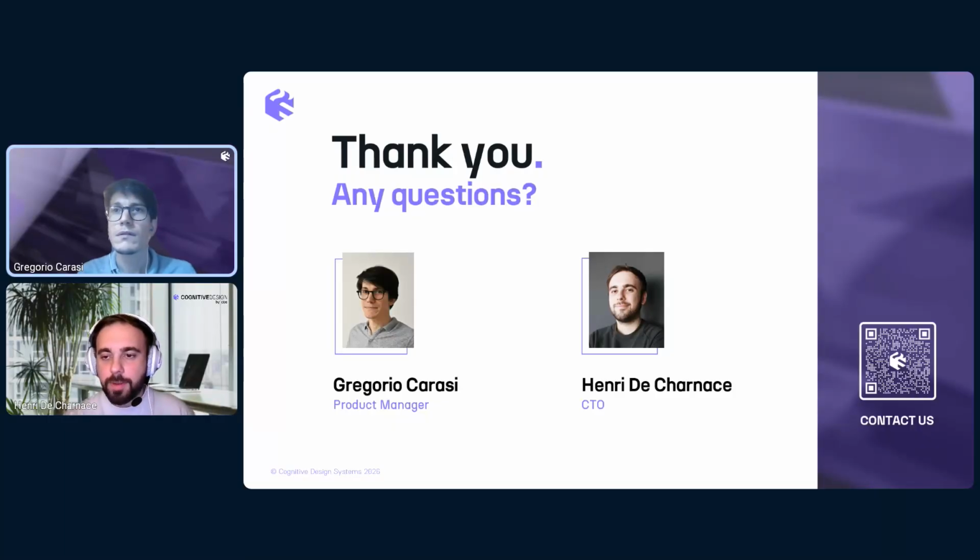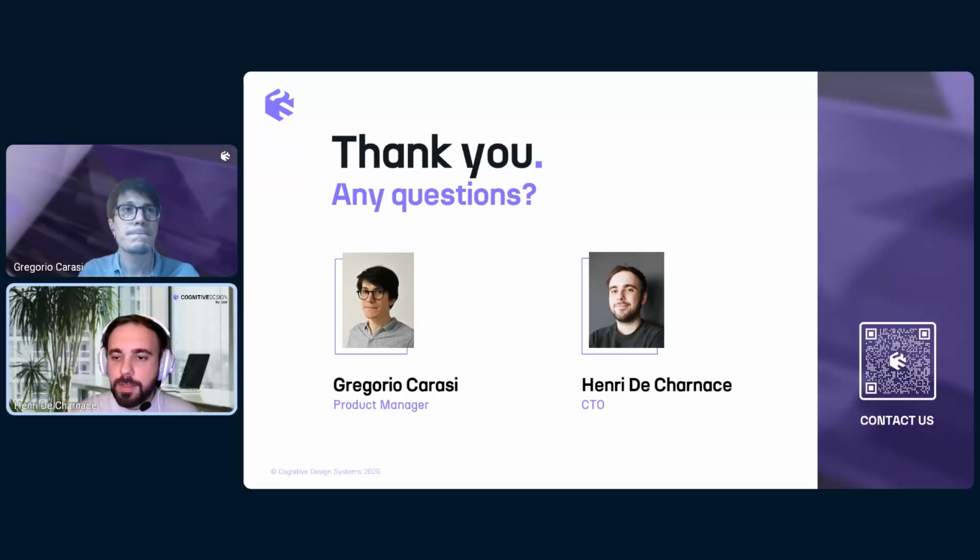And new question from Alexi: is the workflow automated within CDS, prepare geometry, mesh, send to solver, get results? So I believe it's for the CFD export. So regarding the VoxShell partnership that we have, right now, it's not yet integrated. You just have like VoxShell running next to Cognitive Design. You import your part to it and you mesh the geometry. But in the midterm, we plan to integrate this directly inside Cognitive Design, so you can directly export your setup file as a .inp, for example, to directly use it in Fluent or other CFD softwares.